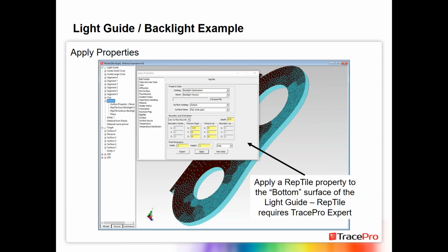And in this example, they're little half millimeter radius hemispheres that are used as light extractors. So they break the TIR in the light guide and direct the light towards the target or the user. And you can vary the distribution of those around the surface to eventually try to produce uniform illumination.